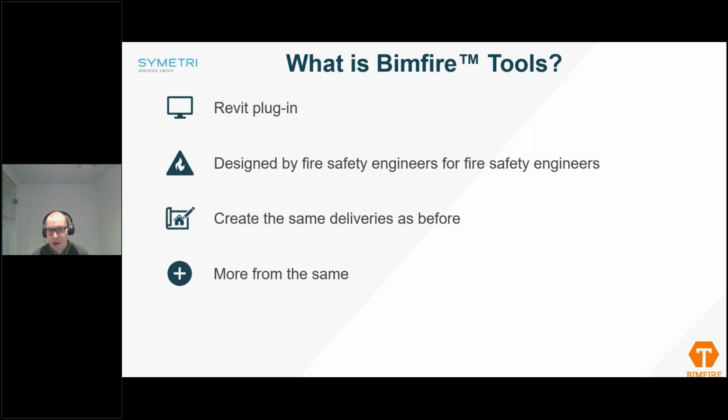Basically, when we are drawing in the 2D world or 2D floor plan, it looks the same. We have the same symbols. But what will automatically happen is that everything in the fire safety model is a 3D symbol. It's for two main reasons. One is, of course, we have to work in 3D. This will mean that when you link a fire safety model, you will automatically see everything by default. You don't have to do any by link view or anything like that.